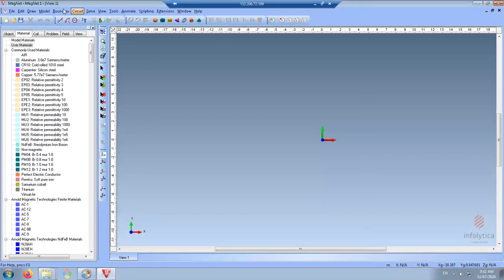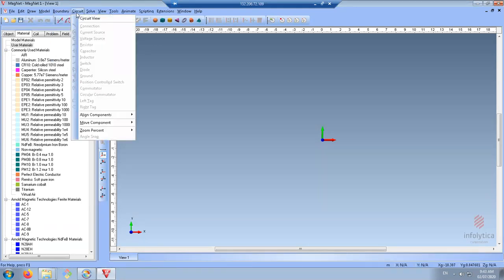So if you are not familiar with boundary conditions and the different options that we have, I would highly recommend reading about them, because these are really useful, especially when you want to deal with a large model. You can easily cut it to symmetric components and just simulate that single component. You have different options, for example, flux tangential, flux field normal, even periodic, odd periodic. These two can be used in motors and generators. There are also some other options that are used mostly in 3D simulations.